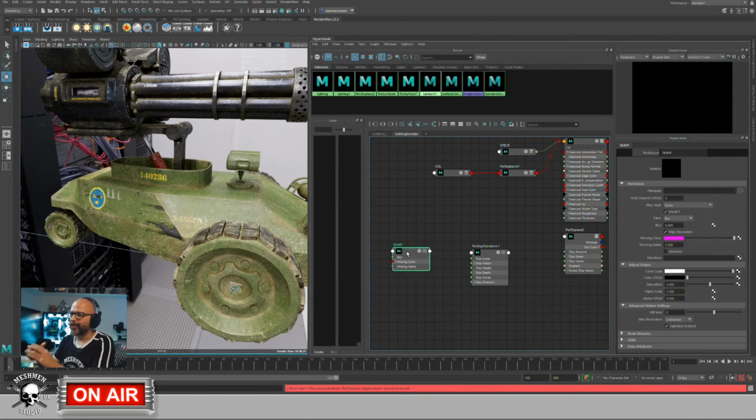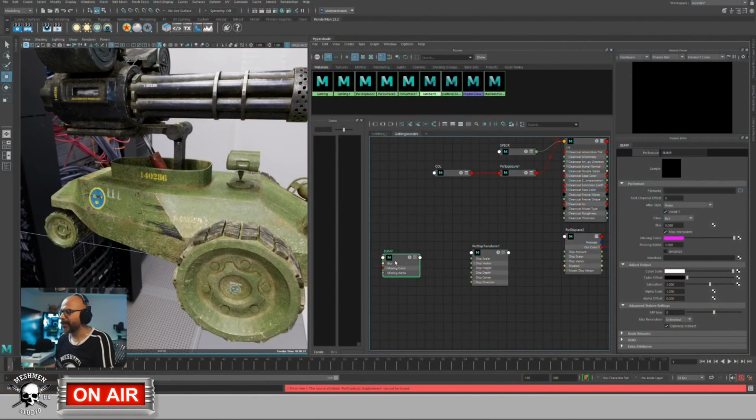So in my example here, my bump map that also doubles as a displacement map is painted with 0.5 value, like zero displacement is 0.5. So anything above 0.5 will be pushing above the surface. So if we imagine 0.5 is no displacement, and 1 will be pushing it up to here, and 0 will be pushing it down to there. So yeah, that's how I texture it. So it's going to be clear soon here.